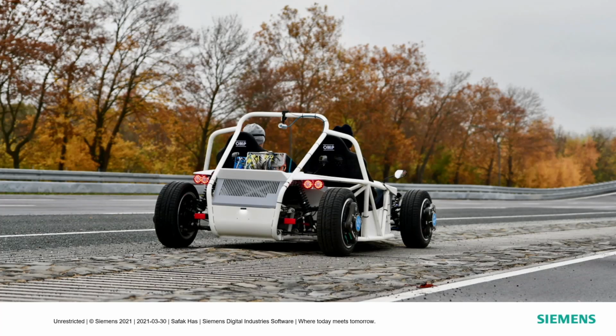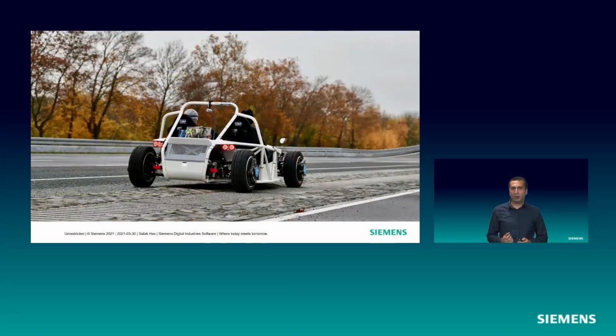The car you see on the screen was actually instrumented with many different sensors, like wheel force transducers, as you see on each of the wheels, let's say. So we put a lot of strain gauges all around the car. We put a lot of accelerometers. We put a lot of displacement sensors in order to understand the operational conditions which are affecting my car completely, let's say. But there are also some difficulties and some challenges present in this picture as well.